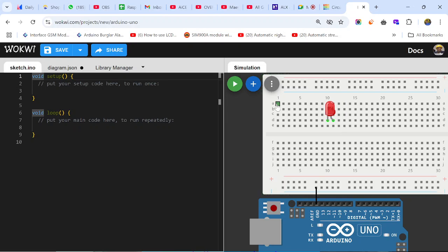So as you can see, let me explain how the breadboard works. You can see this first hole, A, B, C, D, and E, they are internally connected. So if I connect 5 volts to this E, we can get the 5 volts from these other pins. Inside the skeleton of the breadboard, we have some connections there. So also this one and this one and this one and this one, they are connected internally. But for this one and this one, they are not. They are not internally connected.